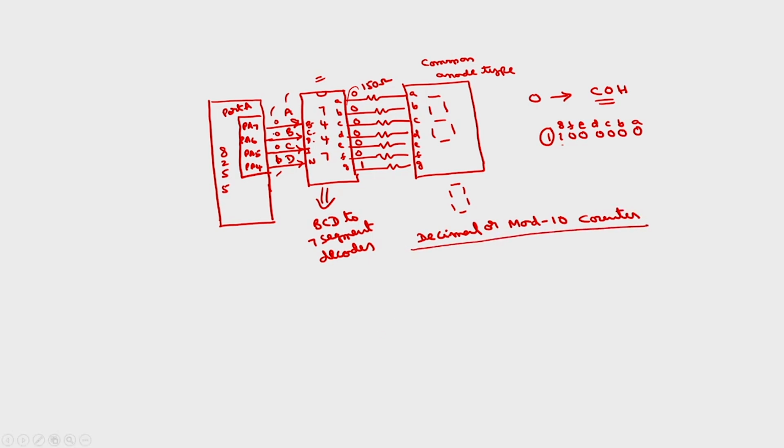Here basically you have to give only 4 bit BCD. So, you assume the same locations: move AX comma 5000, move DX comma AX. Then these connections are, we are assuming we only have to give output, the BCD. Here also you have to program all ports as output ports in mode 0. So, OUT FFH comma AL. These two instructions will program all the ports as output ports in mode 0.